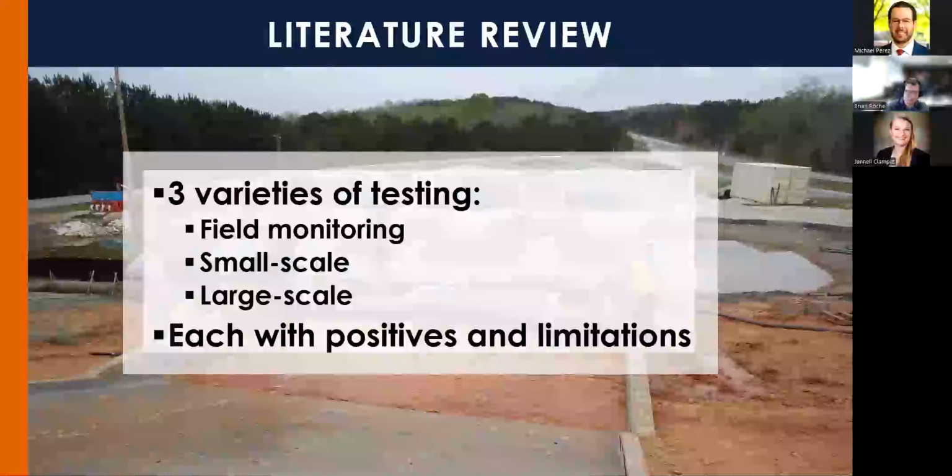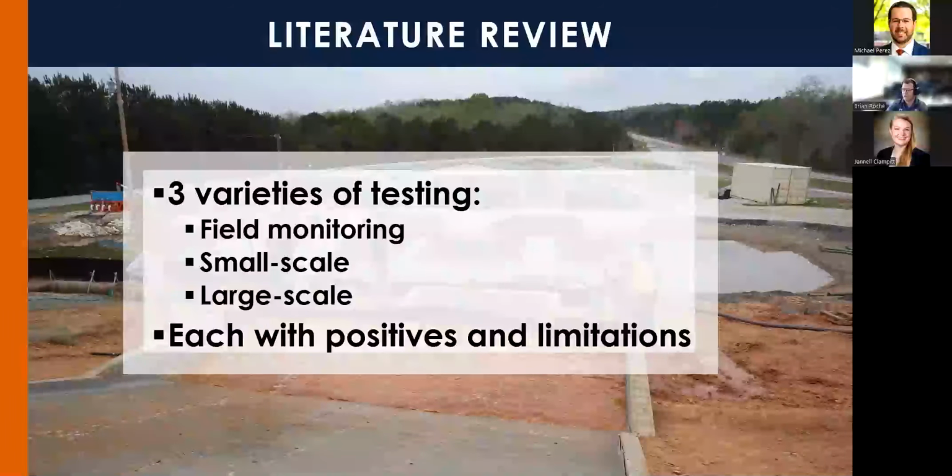So we saw that there are three main varieties of testing. There's field monitoring, where you monitor a sediment barrier installation on an active construction project. Small scale testing, typically in flumes. And then large scale testing, where you evaluate a representative section of a sediment barrier under controlled conditions. And each one of these has its takeaways, but also its limitations.